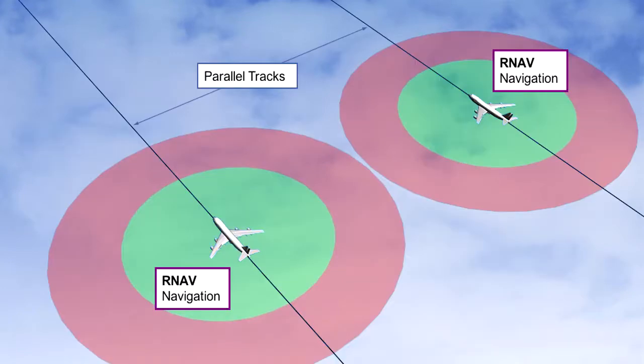For aircraft using area navigation, RNAV, within defined airspace, or whilst on parallel routes where RNP is specified, the lateral separation between aircraft flying using RNAV may be obtained by requiring those aircraft to fly the centre lines of the parallel tracks or ATS routes, spaced at a distance that ensures the protected airspace does not overlap.